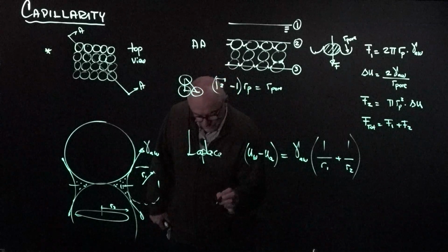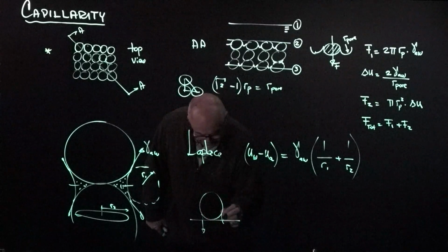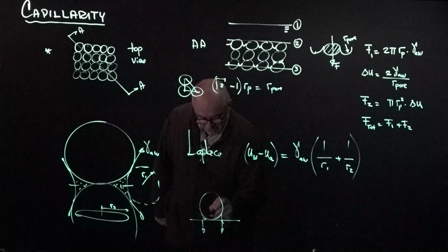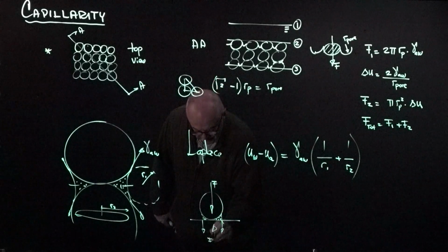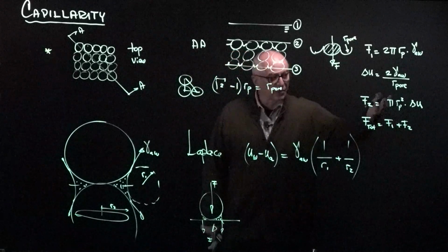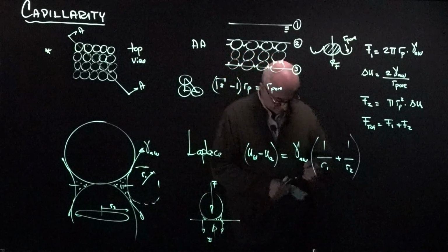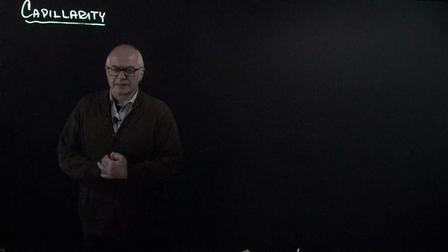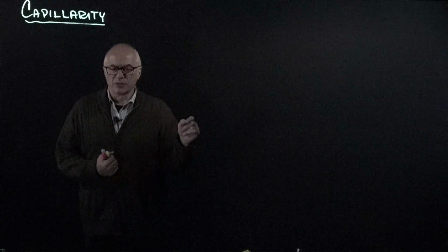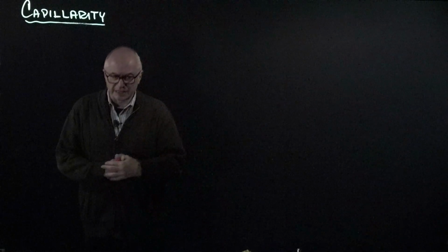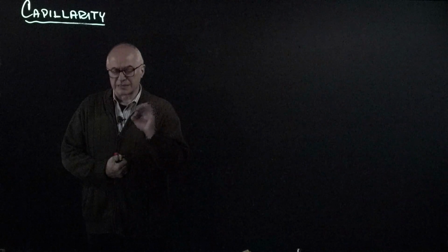And we can go and recompute the forces that now are exerted on the particle. If this is the meniscus and I draw a free body diagram, I have the surface tension along this perimeter, pulling the particles together, and the suction in the water, bringing the particles together, and that gives me the total net force that is acting between neighboring particles due to capillarity, similar to what we did here. There will be two force components. The one caused by the suction is significantly larger than the other one. Notice that in Laplace's equation, the radius R1 and the radius R2 actually have different signs. So if you measure the radius from the outside, one is positive and the other one is negative, and it has to be consistent with the negative pressure that you actually conclude takes place inside the meniscus.